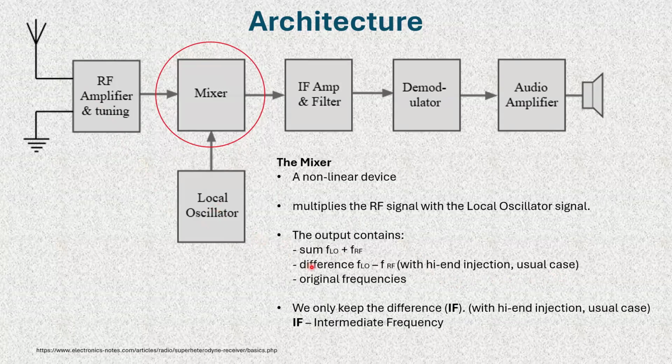Because the sum of this frequency here, so here's the difference, this one minus that, or this one minus that, or this one plus that. The reason for that is that lower frequencies, because microwave frequencies are higher than the VHF region, it's just easier to generate a stable lower frequency than the higher frequency. Within the VHF it doesn't matter.